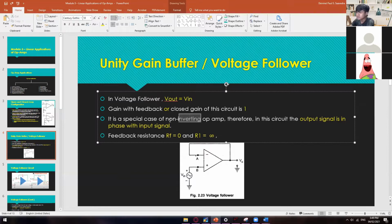Then, of course, this one is similar to the non-inverting because your input is on the non-inverting side, and it also has this feedback resistor. But then again, it's a special case. So therefore, in this circuit, the output signal is in phase with the input signal. So how did we know that the output signal is in phase? That's because your input is in the non-inverting.